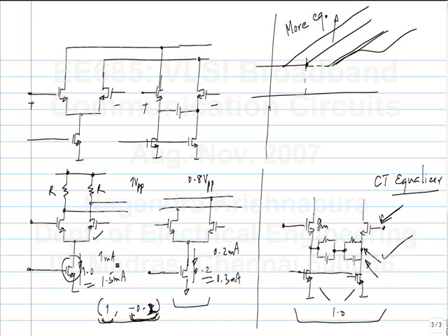So one crude way of doing it is in the frequency domain. Let's say your channel has a certain attenuation at fs by 2, okay? You want to place the 0 so that you get back a boost equal to this much at fs by 2, okay?